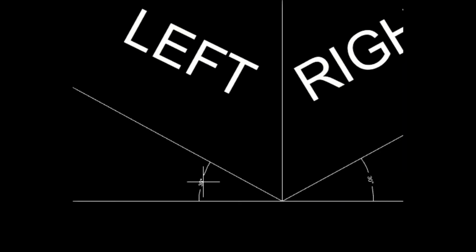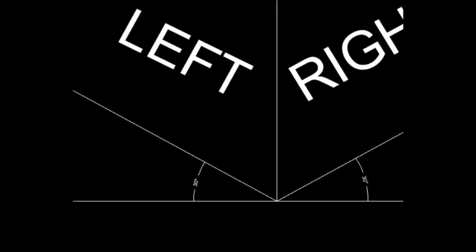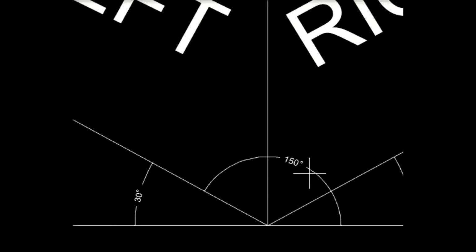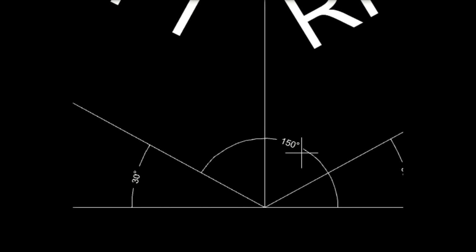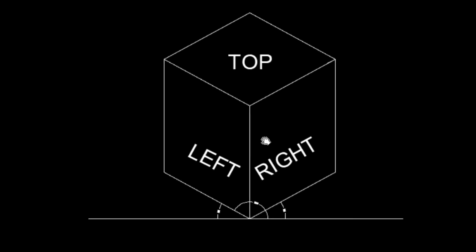But for all calculation purpose, it takes into consideration 150 degrees, starting from 0 in the anti-clockwise direction. Particularly when you are going for dimensioning, then this 150 degrees will come in handy. So with this knowledge, let us start on our journey to learn to develop the skill of creating isometric drawings. Let's start.